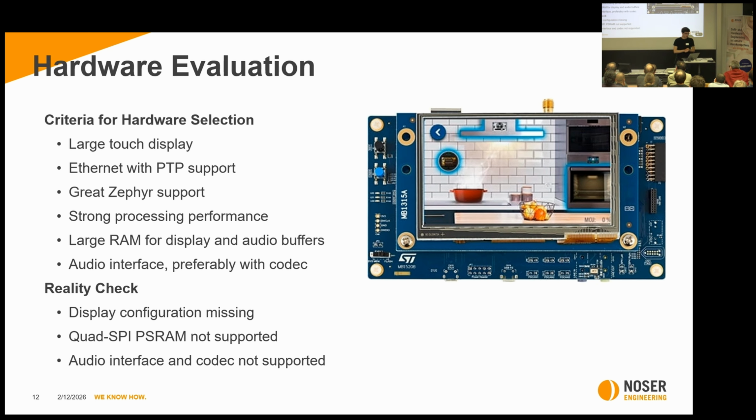Second, I needed a lot of memory for the display buffers, but the onboard quad SPI memory was not supported. So this took me also quite some time to get my memory initialized.